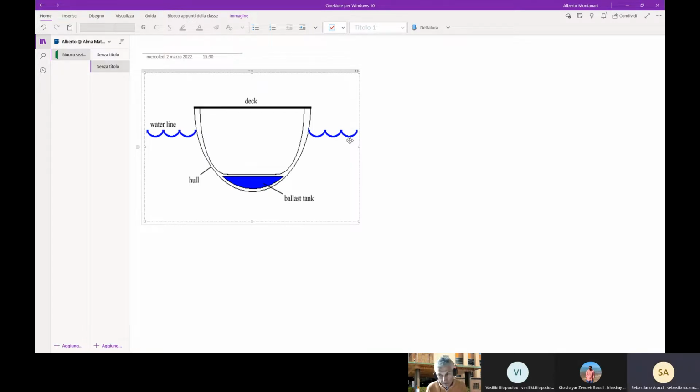So, sorry, Professor. Yeah, please. This is due to the fact that the weight drags the hull more underwater and there is less surface. Yes, this is the first reason and the most important one. But if you think also of the stability, the ship is more stable. So basically, you are less likely to get rotations around the vertical axis, and also rotations around the longitudinal axis, I will explain the term to you later. You have less rotation, and then when you have less rotation, you have less mooring forces. Okay. Did I answer? Perfect. I would appreciate very much if you step in when you have any question for me. Please don't hesitate to step in when you have any question on that.